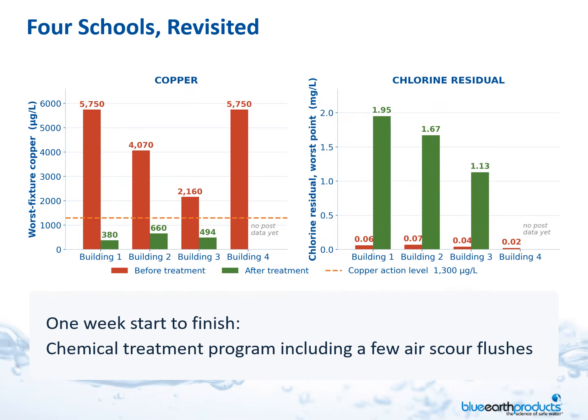So back to those 4 schools. Basically 1 week from start to finish, this was an intervention, and it required an aggressive chemical treatment and a few air scours. But look at the difference. We went from copper levels in the thousands down to well within below the action level, and the chlorine residuals returned back to where they were.